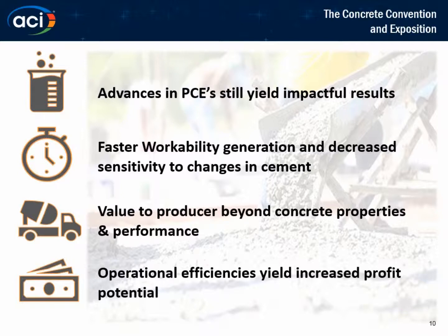And then I know you talked about mixing. Did you do any studies with the effect of over-mixing with these dispersants and how that may affect the properties? Off the top of my head, overmixing in terms of extended mixing? Yes. So extended mixing is common practice for us to evaluate, and yes, the extended mixing had no negative impact beyond what you would see with a traditional PCE. There was no difference. Thank you.